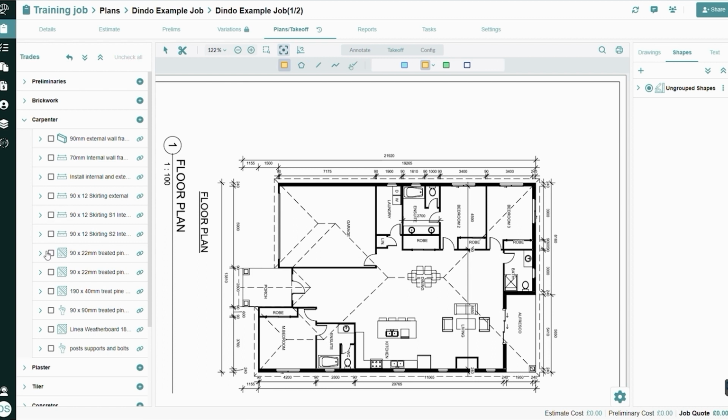If I change that and if I pick an area, it'll only show me takeoff tools that let me do an area, because an area has to close. Similarly to a volume, the shape you draw has to close in some way so that it can complete the volume, okay? So those will all change depending on what you tick. If I tick a count on its own, you're just going to get the count feature. So that'll be dynamic as you're moving through. As you tick different things, it's a dynamic button bar is what it's called. So they'll change all the time.